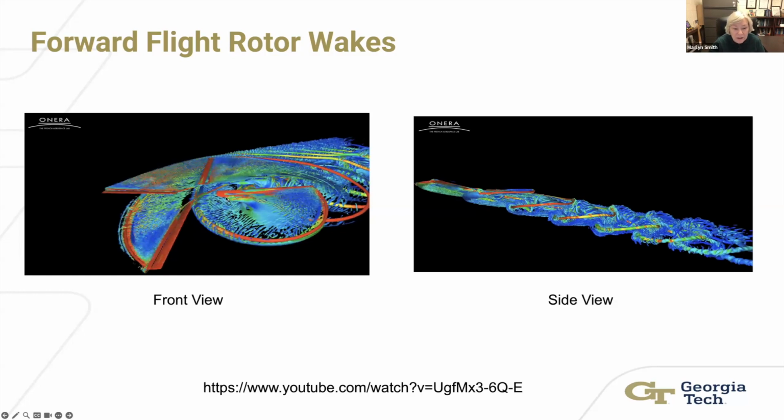You also see then that you have a vortex sheet being shed here. It's not simply at the tip, it's all along here. And if you have any discontinuities, you're going to see more wakes. Here's another tip. This is a root vortex coming off the root because it's a finite blade.